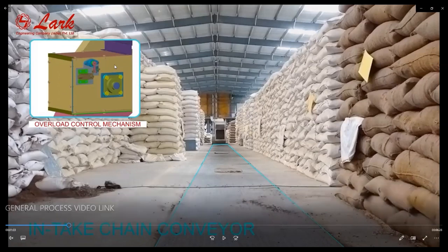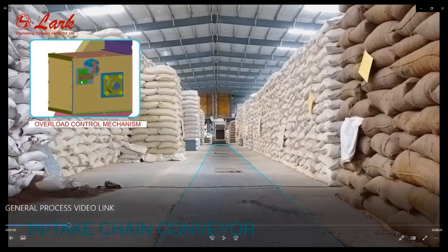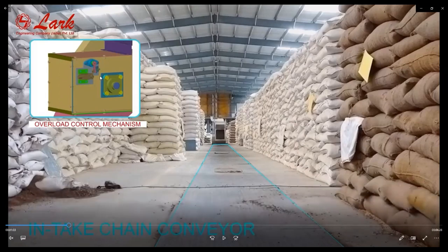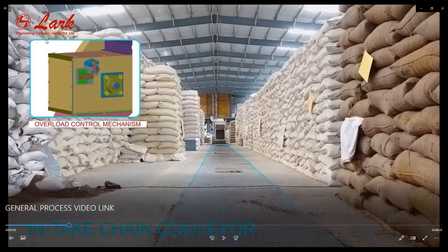Even we can install this overload control mechanism in existing and old projects or projects of any company. Even the chain conveyor of any company, we can put this small thing. This is very cost effective, just a limit switch, a flap, and the hinge. Very cost effective thing that can reduce our maintenance cost and running cost or the breakdowns of the intake chain, because the major part in the batching breakdown is the failure of the intake chain gearbox or the scrapers, or the bending of the moving parts due to the back pressure of the material due to the jamming at the intake elevator. So this is a very crucial thing that we can check with our chain conveyors in the batching process.